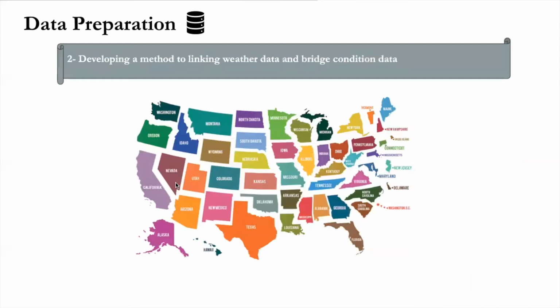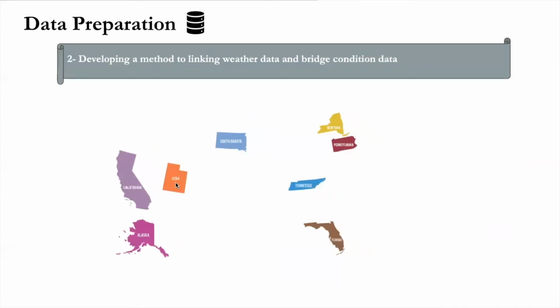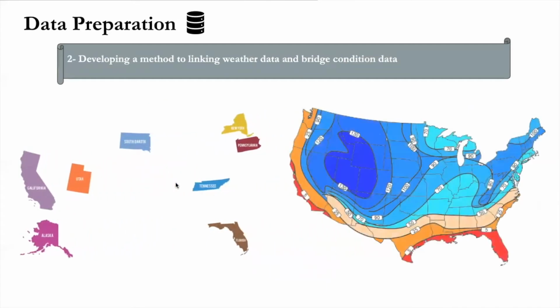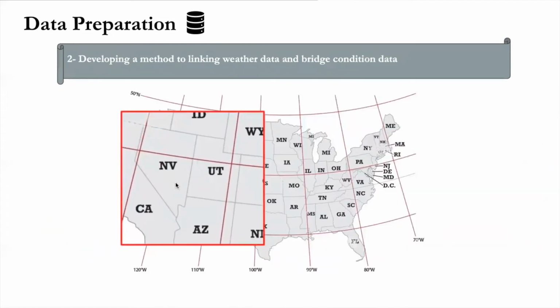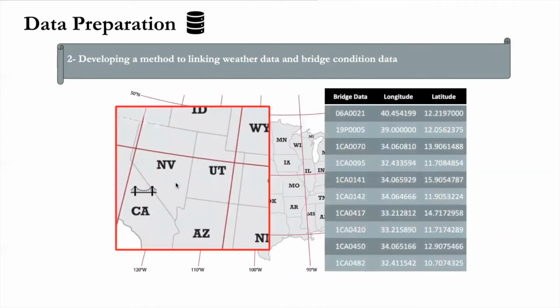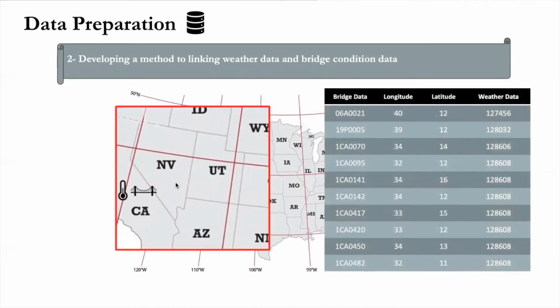In this study, 8 states were selected based on the weather data and the freeze and thaw cycles, so we can have a good range of weather conditions. To flatten the data, we use geographic features. Coordinates in the two data sets have been rounded for the concatenation. With this approach, each bridge can be assigned to a weather data with a half a degree accuracy. Moreover, we used weather data for the neighbor states, to ensure a matching regardless of the weather station location.